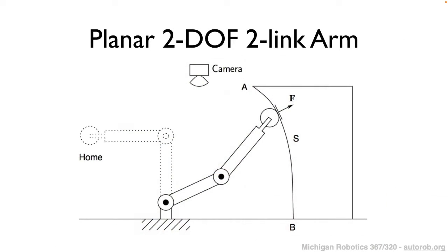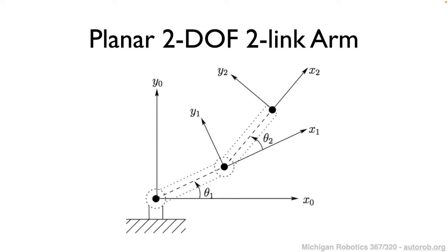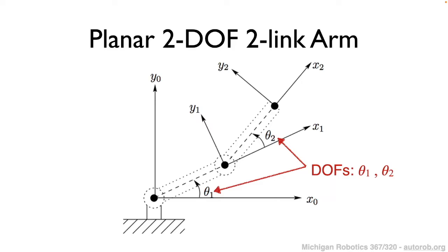And so in this figure, we're taking a bird's eye view of the two-link arm and a conceptual model so that we can fully observe the robot's configuration. And so if we look at this robot again and consider what the state of the robot can be represented as, we'll first note that we have 2 rotational degrees of freedom for this two-link arm. The first degree of freedom being theta 1, and the second degree of freedom being theta 2, as shown in the figure here. And in addition to these two, we also have 3 rigid body links.